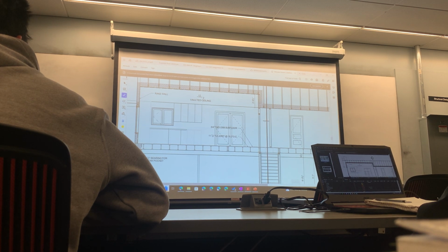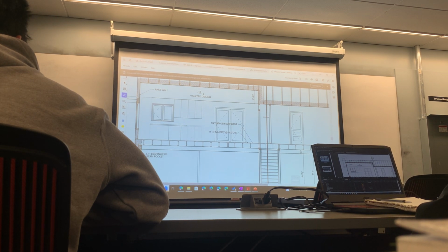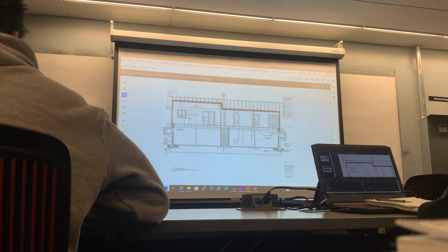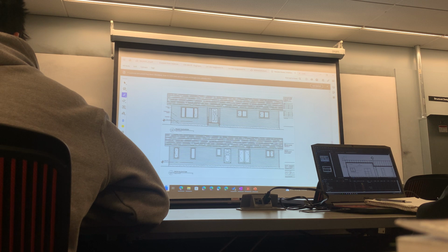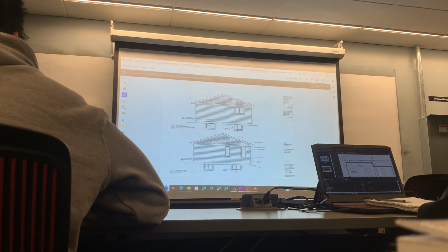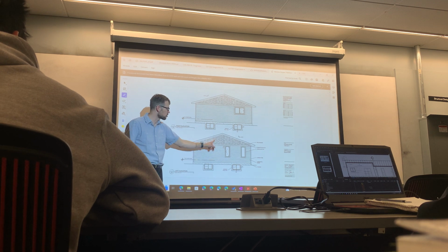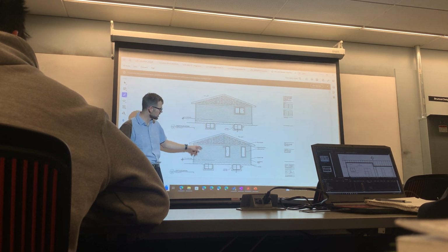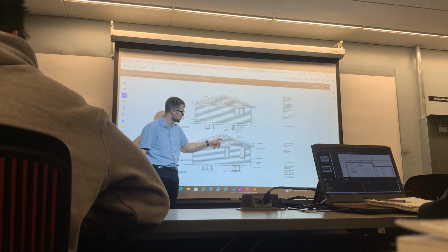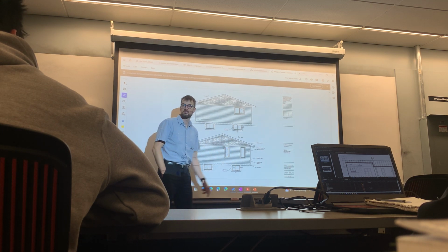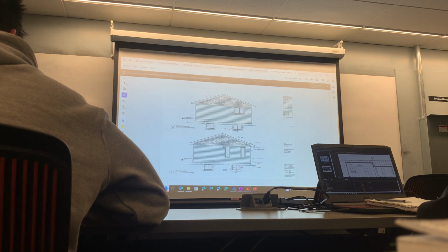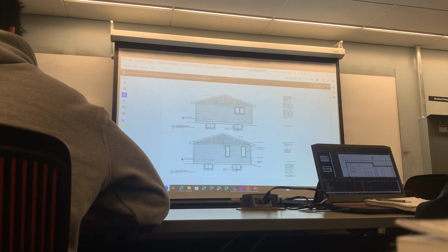What would the view be if we're looking from the left? For that, we have to look at the elevation. So let's say that's the north and south walls, front and back. Here, it looks like a truss, right? But here you might construct a raked wall, where each stud is getting successively longer and then shorter. If there was a truss with a vaulted ceiling, so you don't have a roof raised wall,